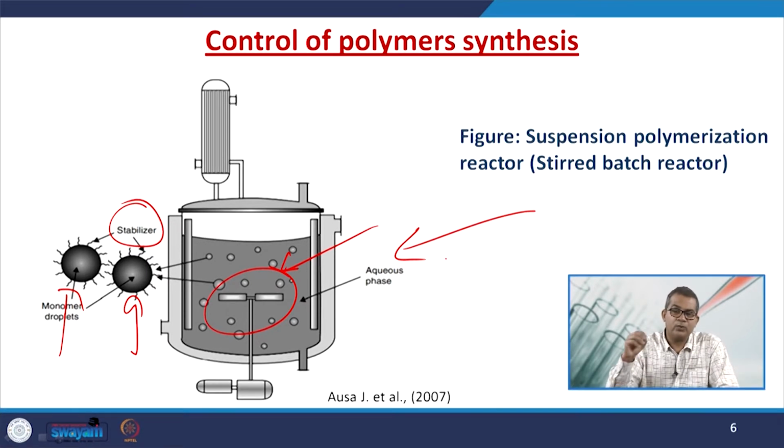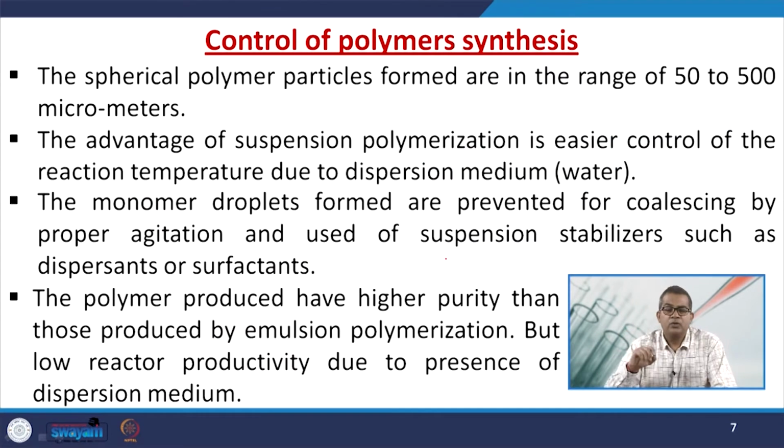They are very good support for catalysts, and they are used as different types of supports for ion exchangers. So, when we see these polymeric beads, they are spherical in nature, and usually they are in the range of 50 to 500 micrometers. Now, it depends on how much surface area we require, how much porosity we require. Moreover, it depends on which system we are going to use it in, because a larger particle size sometimes may adversely affect the pressure system, etc.